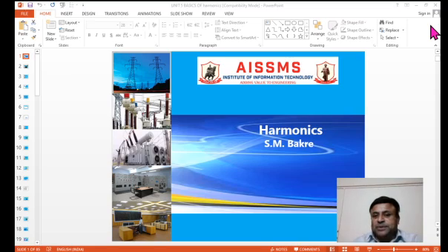Connect CRO to your place where you are sitting and remove the computer from the supply or switch off the computer. Now if you observe voltage and current waveforms on the cathode ray oscilloscope, then you will observe that they are purely sinusoidal. Now in the second step, switch on the computer and printer or any other electronic devices.